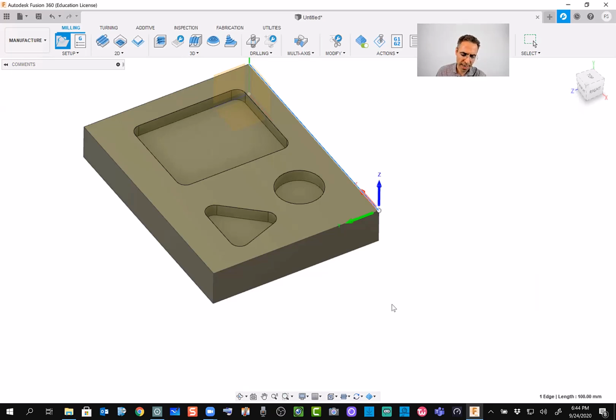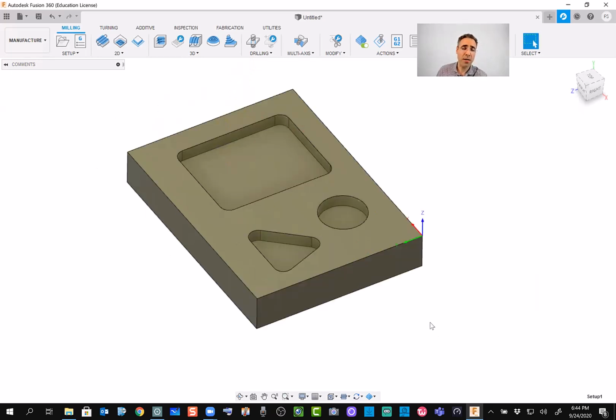All right, so I just click OK. So this is what I have here. I did my setup. By setup, I did two things. I don't have any extra material to be removed, and also, I defined my coordinates. I pick a corner because a corner is the best place. Later, when I place this on the machine, I move my tool to this point and click on the home key and say, this is the zero point for the tool. What is the next step?